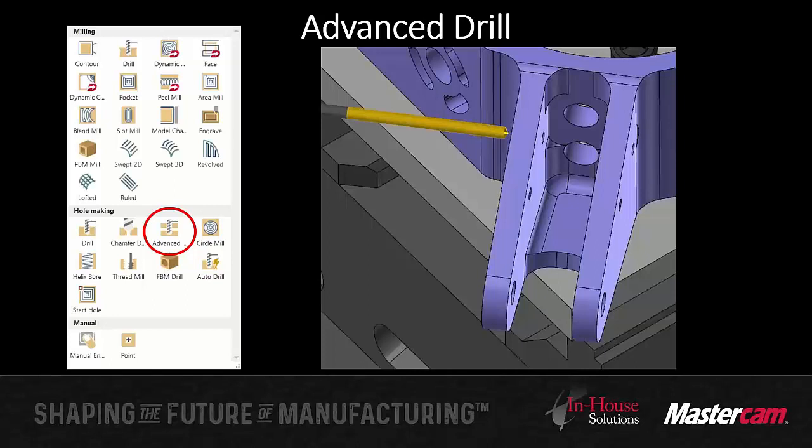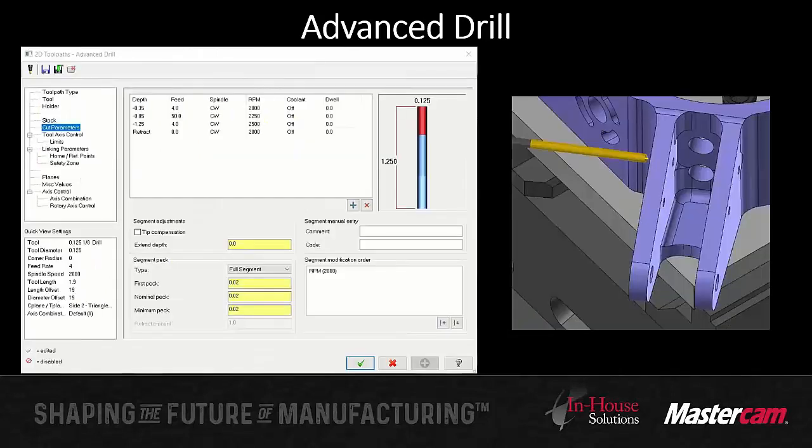Quite often on a long drill series, the tooling supplier suggests you go with a lot slower RPM and a slower feed rate until you get to a certain depth, and then ramp both your feed rate and your spindle speed up as you're drilling right through. So even if it's a solid part, you'll want various speeds and feeds. This gives you the ability to peck through certain areas, rapid through others, and just drill through others, while incorporating various different spindle speeds, coolant modes, anything like that.